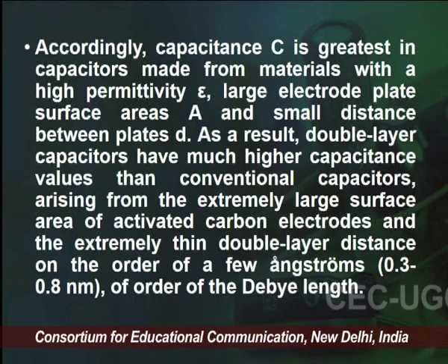And moreover, the ability of the electrodes to accomplish pseudo capacitance effect by redox reaction, intercalation or electro-absorption strongly depends upon the chemical affinity of the electrode material to the ions absorbed on the electrode surface, as well as on the surface structure and the dimensions of the electrode pores.